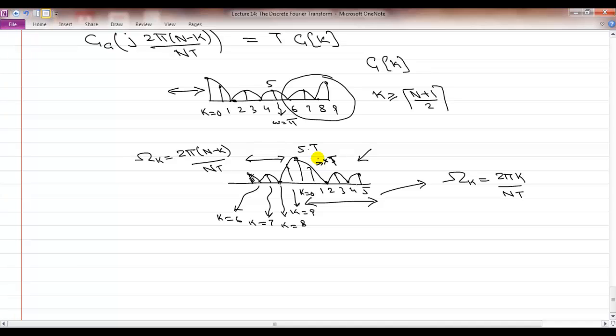Okay. So spectral analysis is pretty much about you do the DFT and then it's really asking you how do you interpret these sequences that you have gotten, and the way you interpret them is through relabeling of the x-axis by doing a function of N and T, and also relabeling of the y-axis or rescaling of the y-axis through multiplication with T. And then whatever plot you look at, you say that is a surrogate for my continuous time Fourier transform of the signal.